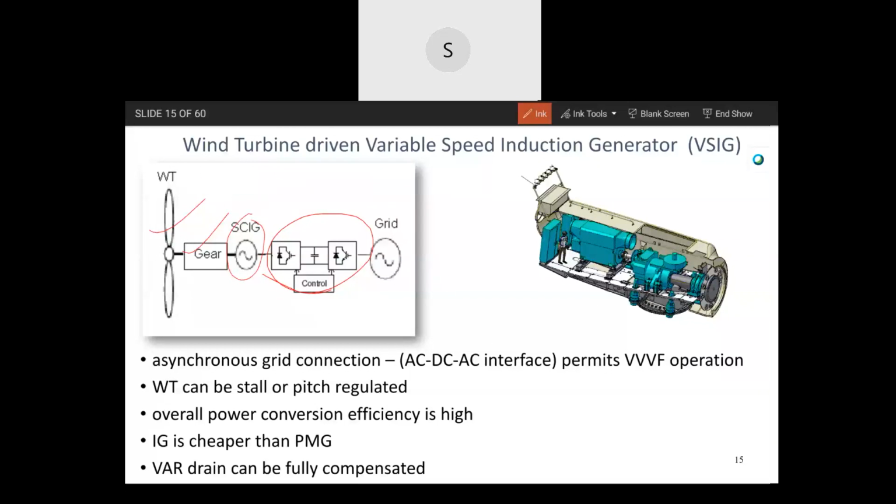But still, some people agreed. Initially, the manufacturer itself developed a wind farm and demonstrated it. Seeing the performance, people started buying it. Later, squirrel cage machine was discarded. Nobody is manufacturing it because there is no demand for that. But permanent magnet generators are more and more used. A large hike in efficiency is possible because if you are using a permanent magnet generator, efficiency is very high. That's why you are using it. But otherwise, the cost of the machine is very high.